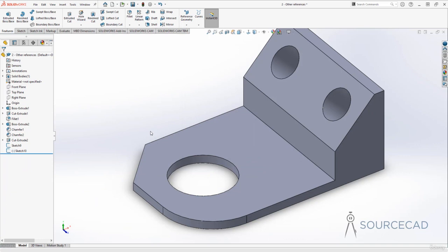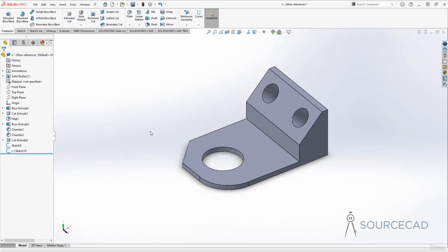Now finally let's talk about creating coordinate system, and you can create coordinate systems using this option right here. Now we already have a basic coordinate system here which is the default one, but if you just want another one for maybe let's say CNC machining, and you just want to specify a different coordinate system which is with respect to your selected part, or maybe you want to specify several different coordinate systems for several different features of your drawing, then you can do that using this coordinate system.